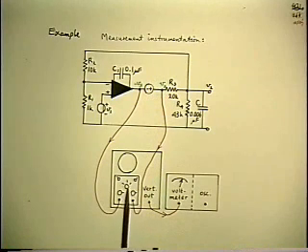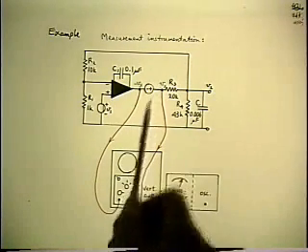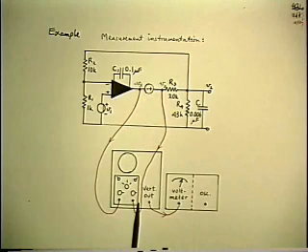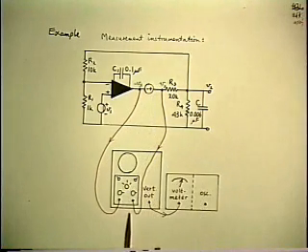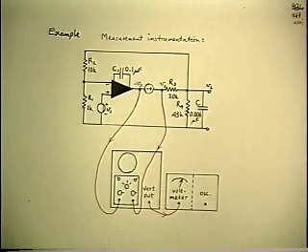And there's another knob on the front of the dual channel preamp that says sum or difference. Or maybe it only says difference, but there's another knob that says invert. So with a combination of the two, you can choose whether you read the sum or the difference of those two waveforms. Which means by measuring differentially, you get a third reading on the meter, which is a magnitude also, but it's the magnitude of the third phasor.